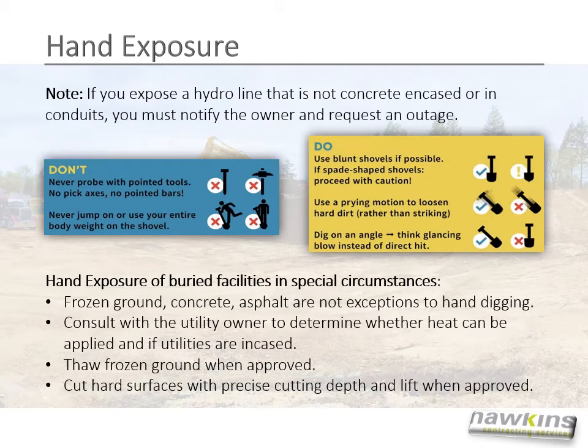During hand exposure, if you expose a hydro line that is not concrete encased or in conduits, you must notify the owner and request an outage. There are other do's and don'ts that must also be observed.